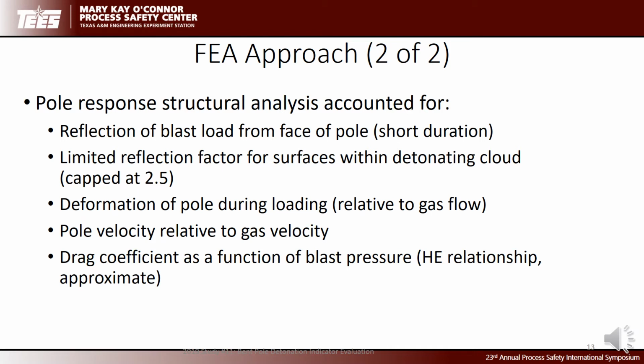The structural analysis tries to account for most of the major effects here. We account for the reflection of the blast load off the face of the pole, although that is of fairly short duration. For pole locations inside the cloud, we limited the reflection factor to 2.5, since based on our experience, that's a reasonable value for a reflection factor inside a detonating cloud.